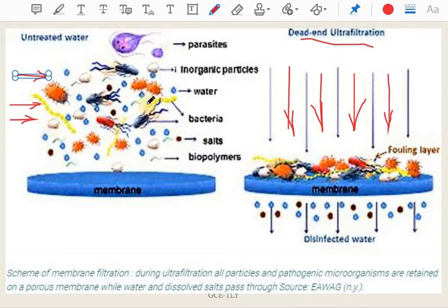As a result, while the liquid passes in a parallel direction, the water passes through the membrane, while the excluded particles, the reject, are carried away by the water flowing along the direction of placement. So this reduces fouling of the membrane. It somewhat extends the life of the membrane used for filtration, and it also increases the efficiency.